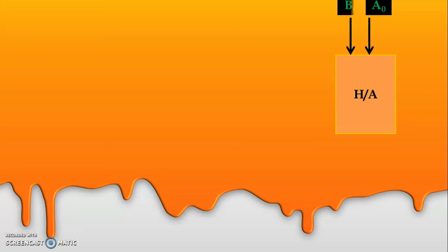Now let us start implementing the block diagram to understand the 4-bit parallel binary adder. We have 1 half adder for the least significant bit. We have A0 and B0, and we have the summation of A0 as well as B0, and that is S0. We have another full adder. Now from the second stage onward, we'll have to take a full adder, because there is always a possibility of the carry, and with the 2 binary bits we have to add a carry also.